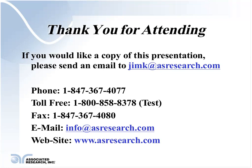Yes, of course, it is very important when you're performing your verification. Going back to the example of the test verification box, it is always a good idea to take into account any lead resistance and any offsets. Make sure to take care of any offsets. And yes, it is a very important thing to take into account all the leads and all the connections for verifying all the different test types.